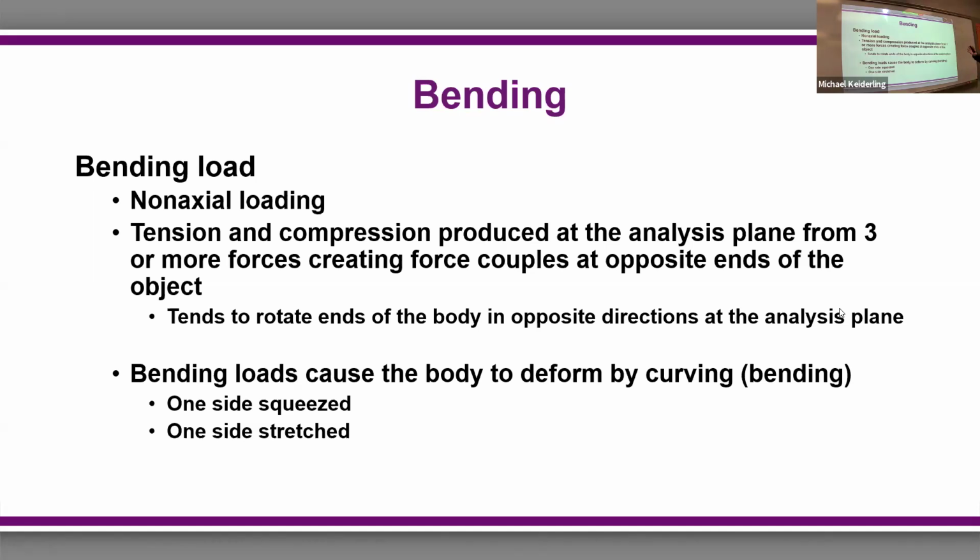There's both tension and compression produced at the analysis plane from 3 or more forces, creating force couples at opposite ends of the object. This tends to rotate the ends of the body in opposite directions of the analysis plane, and they cause the body to deform by bending, curving. One side is squeezed, the other is stretched.